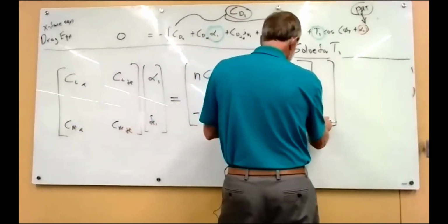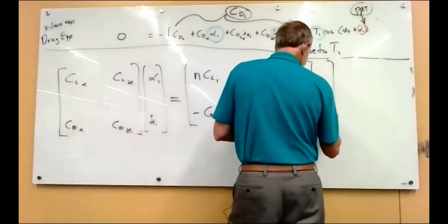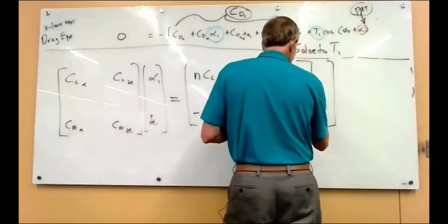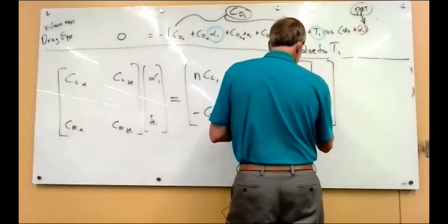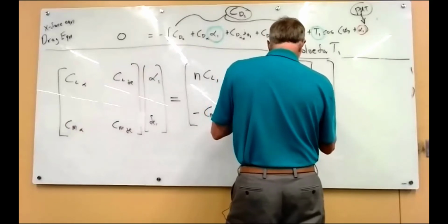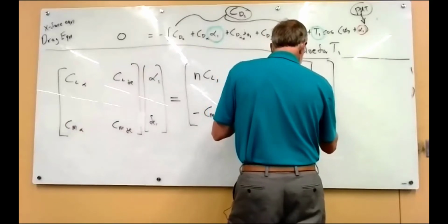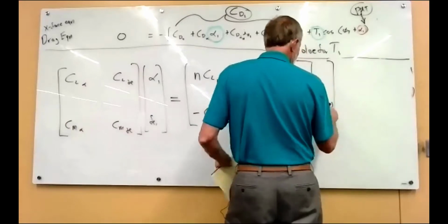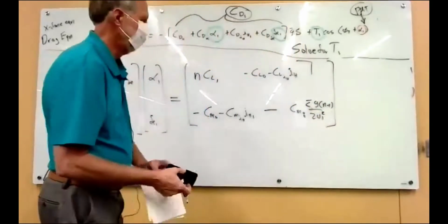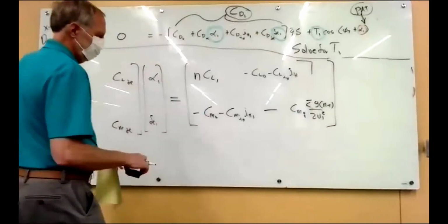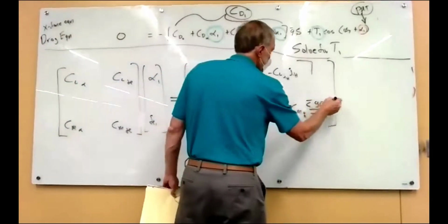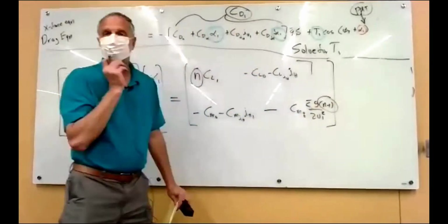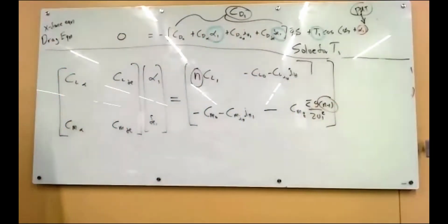And we get another U1 down on the bottom from that, and then the Q gets turned into the load factor representation that we had, which was G times N minus 1 over U1 for that. And so now this problem is in terms of load factor specifying the turn. The turn rate, the pull-up rate is Q, and we've substituted for that in terms of load factor.